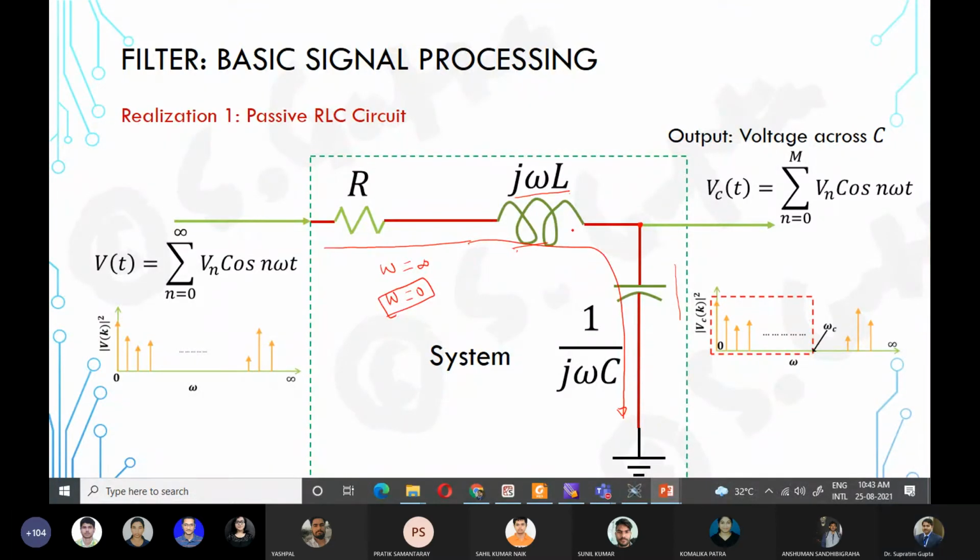So what we'll be getting here are only those components which have this value as not zero, right? The higher frequencies will all die down, and we will only have these values for which this omega is closer to zero, and only some terms which have a significant amount of energy in this band. So effectively what we can develop with these is a low pass filter.